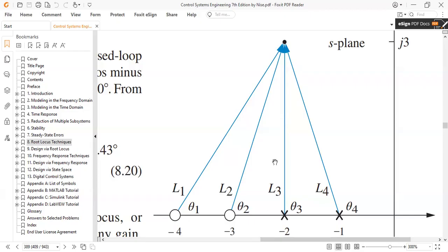Yes, sir. Since we have the point at -2 plus j3, the real axis point for this point would be equal to -2, and the 0 is at -4. So the difference between these 2 points is equal to 2. Similarly, the height of this perpendicular is equal to 3, which is the value of the y-axis of this point. So the magnitude of perpendicular is 3, and the magnitude of base is 2. I want each and every one of you to respond, is this clear to all?